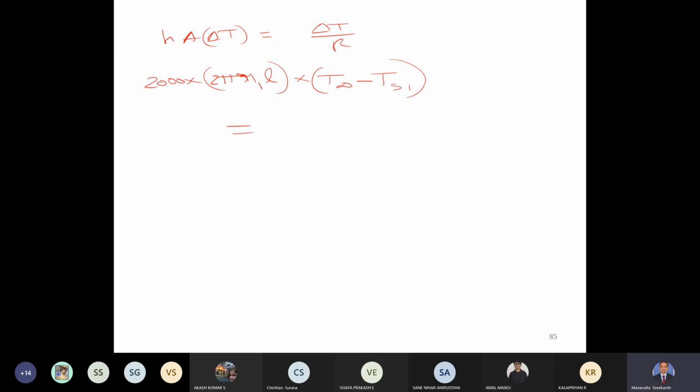cylindrical coordinates. So for a cylindrical shell, we know that the heat transferred is the overall temperature difference divided by the resistance. So this overall temperature difference will be Ts1 minus Ts2 divided by the resistance, which is 1 by pi KL logarithm of R2 by R1. So this formula, we have derived it, we have seen it earlier. This formula is available in data book page 53. Okay, so this is the basic equation that we will be going ahead with and solving the problem.